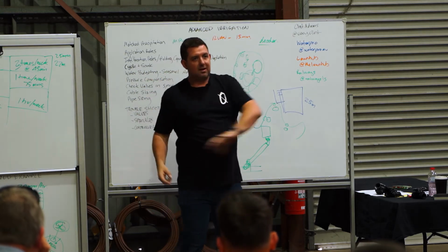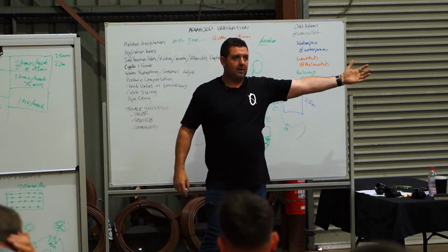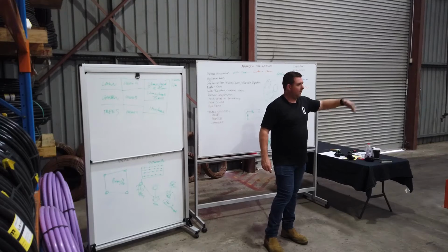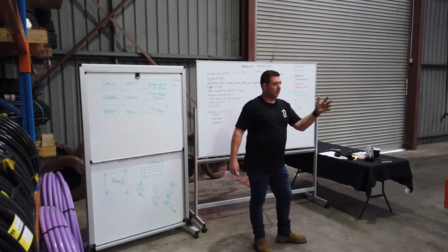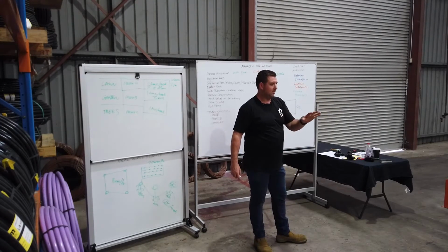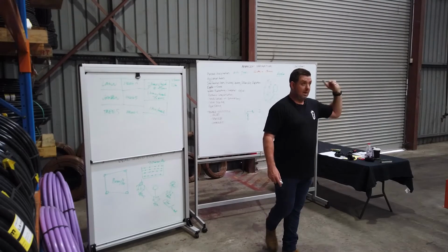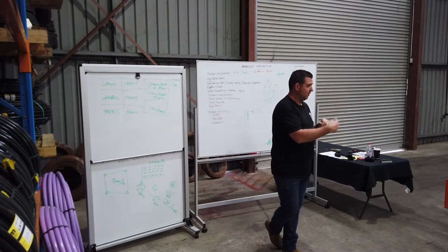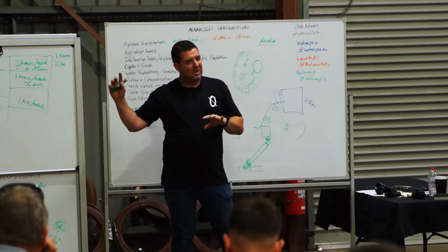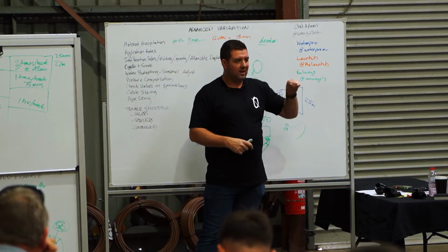The controller sends out a signal, like an email or a text. It'll be a 5-digit code, 90210 for those of you that have, no, that means something for you, I know it does. It sends out a 5-digit code, the decoder goes, oh, that's me, and it opens the valve. So it sends the pulse to the valve, and I think it tells it to close as well. It doesn't just stay open the whole time.